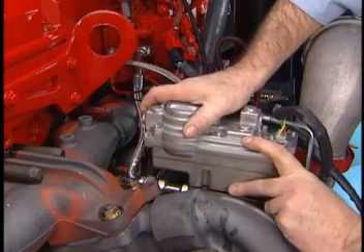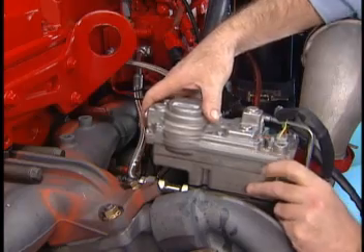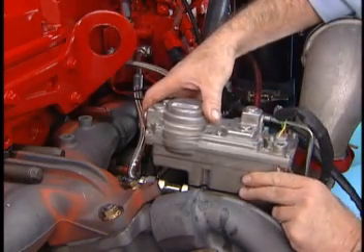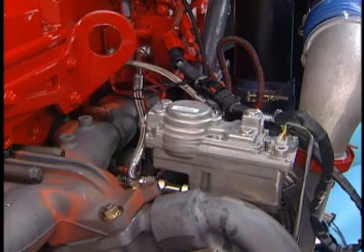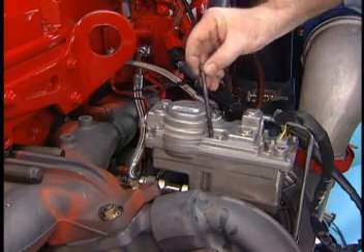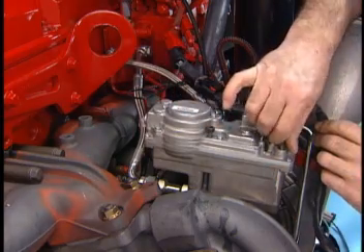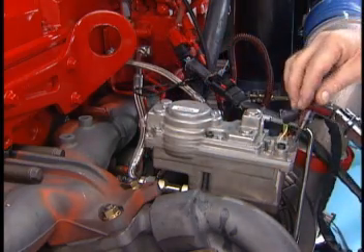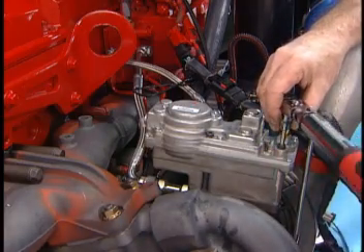The actuator pinion gear and the turbocharger sector gear must engage smoothly. If not, verify that the sector gear through hole and the bearing housing blind hole are aligned. Install the 4 cap screws. Torque to specification. Using Insight, calibrate the actuator.